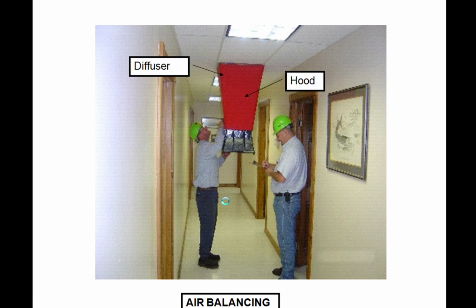There's a readout that can be recorded that says how many CFM you're getting out of that particular vent. You test all the vents to make sure they're coming out at whatever volume they're supposed to, and that there are no big losses along the line, where you're further from the fans or the VAVs, giving you lower readings than you should.